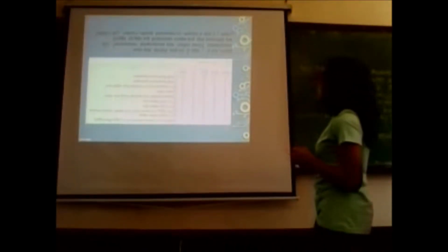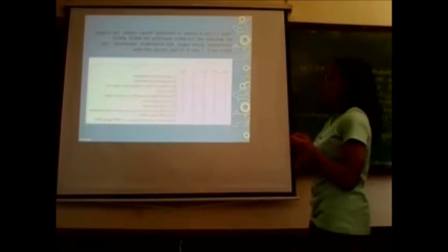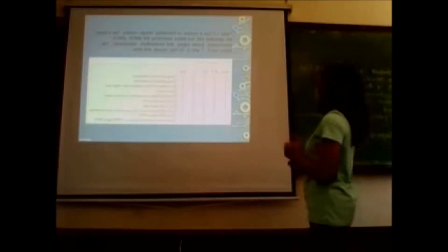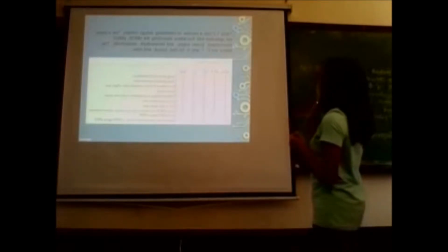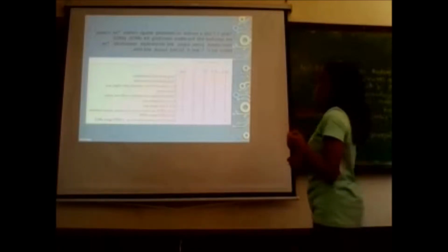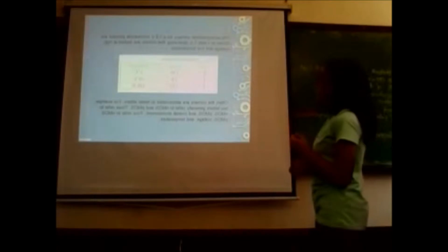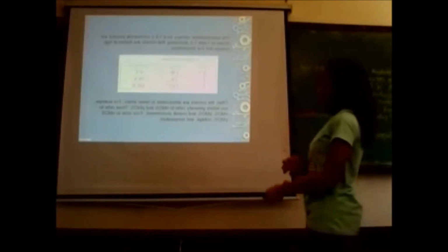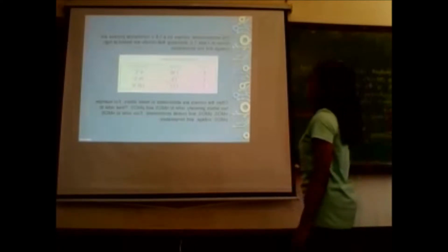This table shows a number of interesting design corners. The corner is specified with 5 letters, describing the NMOS, PMOS, interconnect, power supply, and temperature respectively. The letters are F, T, and S for fast, typical, and slow. The environmental corners for a 1.8 volt commercial process are shown in table 7.3, illustrating that circuits are fastest at high voltage and low temperature.